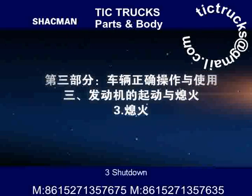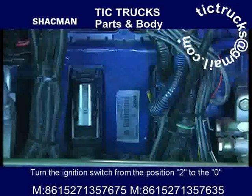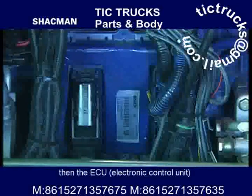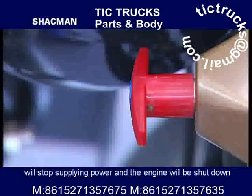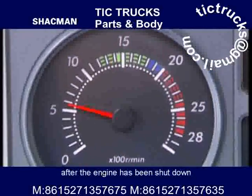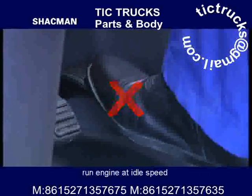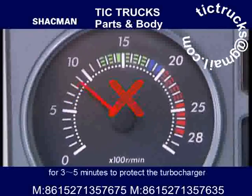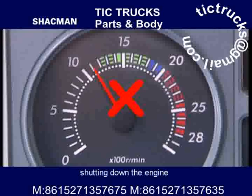3. Shut down. Shut down the engine. Turn the ignition switch from the position 2 to the 0. Then the ECU, electronic control unit, will stop supplying power and the engine will be shut down. Turn off the main power switch after the engine has been shut down for 30 seconds. Before shutting down the engine, run the engine at idle speed for 3 to 5 minutes to protect the turbocharger. It is prohibited to violently push down the throttle before shutting down the engine.